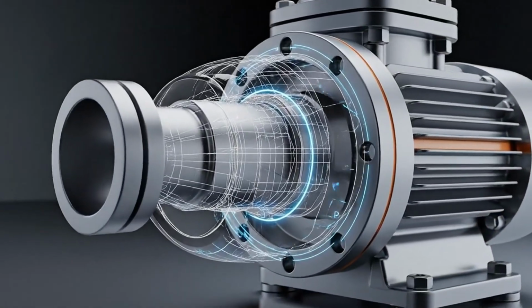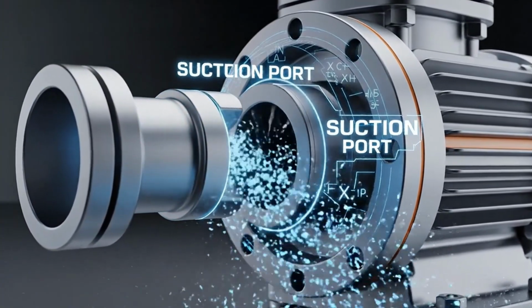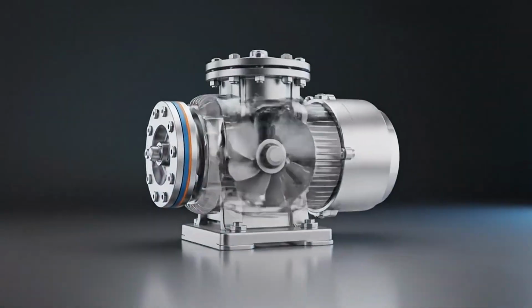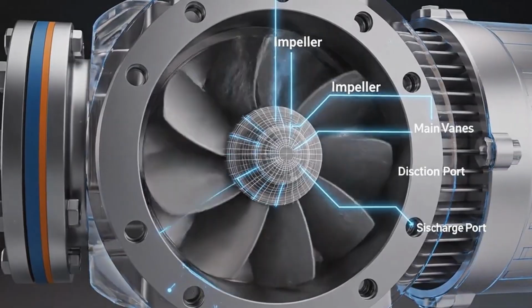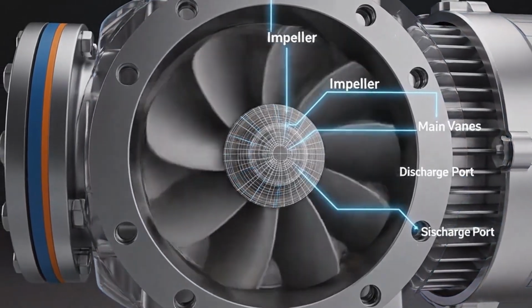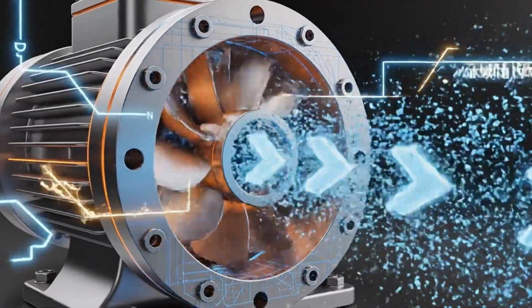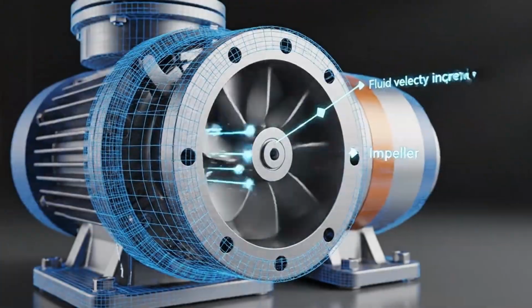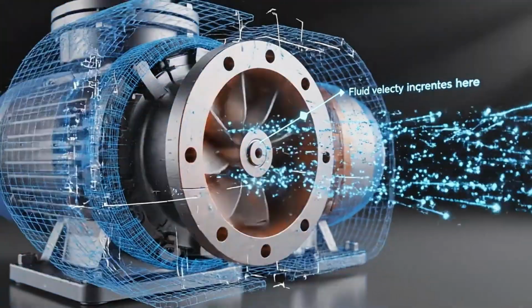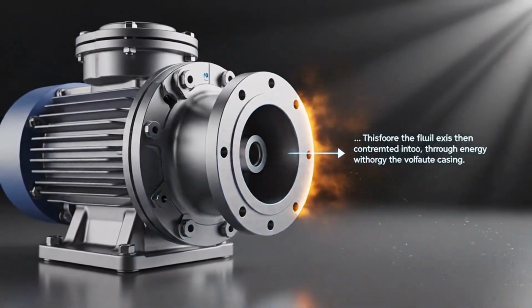At its most fundamental, a centrifugal pump draws fluid in through its suction port. The heart of this operation is the impeller, a rotating component with a series of vanes. This increased velocity is then converted into pressure energy within the volute casing before the fluid exits through the discharge port.